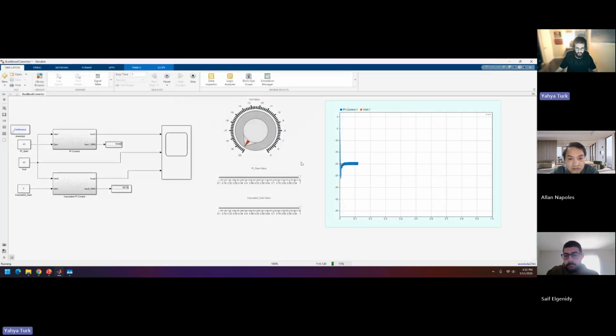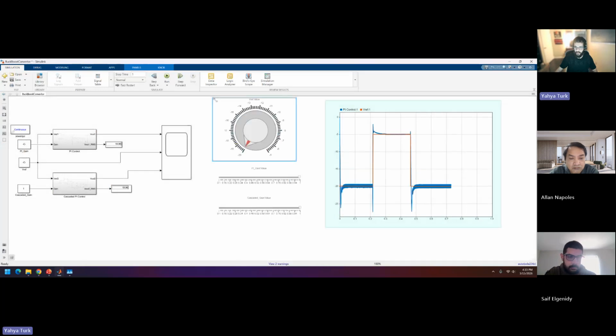And we can see how it handles the transitions. Perfect. So we can see that our voltage ripple is less than 1 volt across that 20, and it's even less at lower voltages and will be less at higher resistance. This is exactly what we expected.